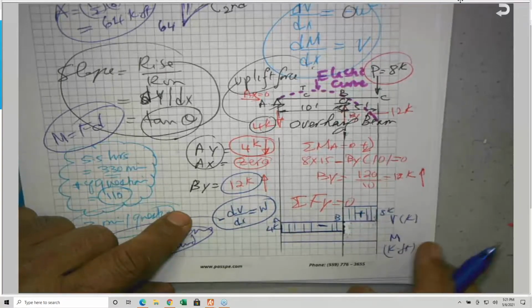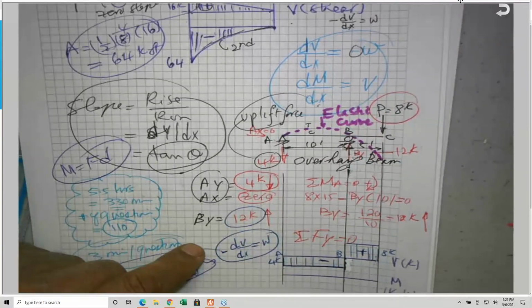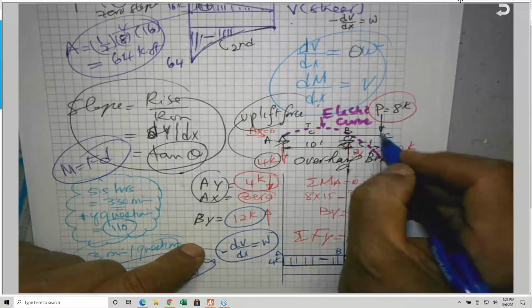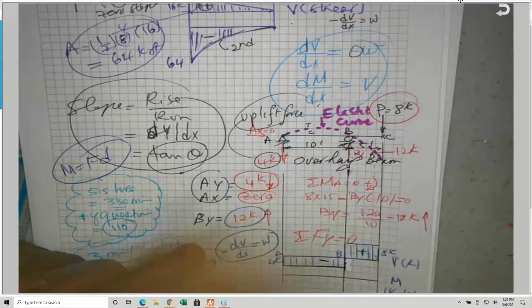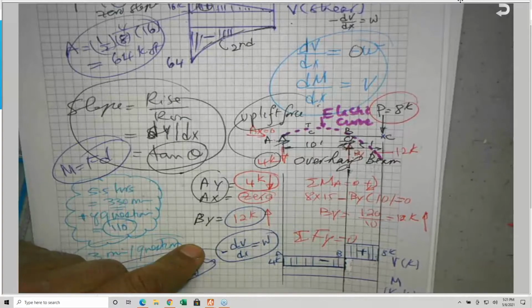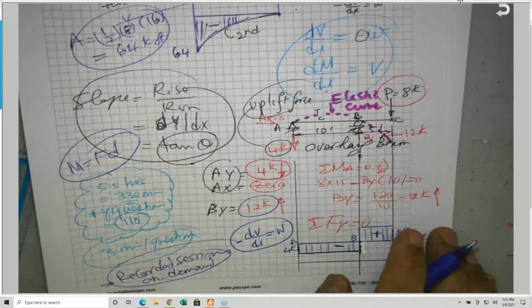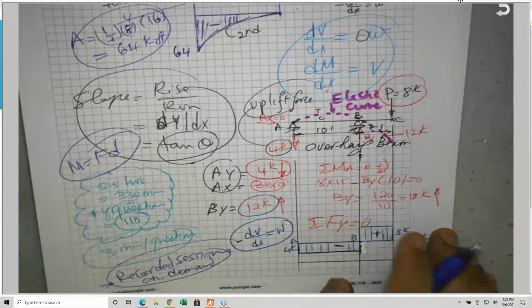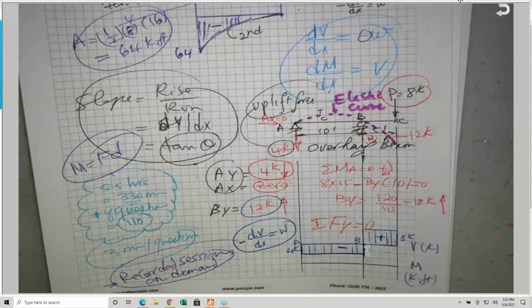If you look at the bending moment, I need you to know key points. The bending moment at C is equal to 0, and the bending moment at A is equal to 0. Why? There is a very important rule, and I'm sure for those who are attending Fresno State in CE1 theory, or even for 121, there is one very important rule I normally mention in the class, and I ask the students to remember this rule very well because it will help them.